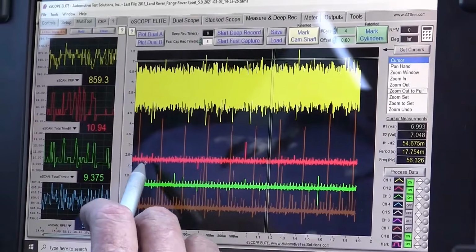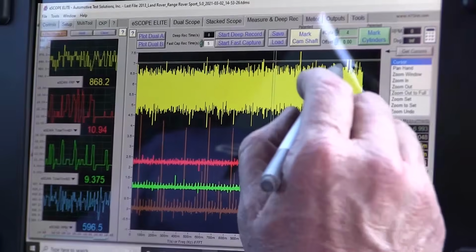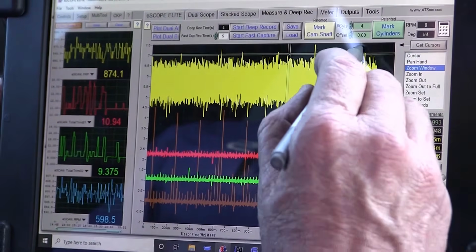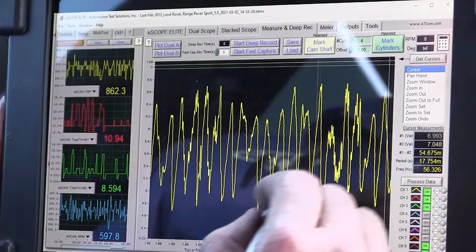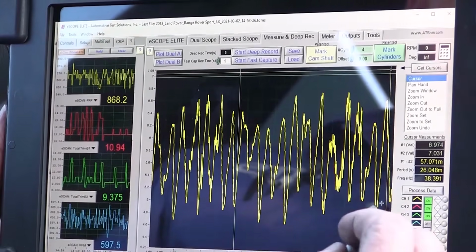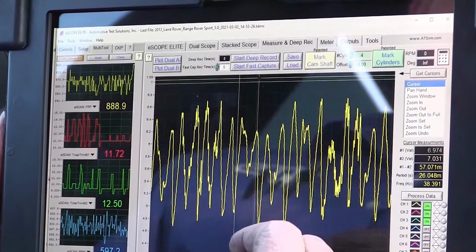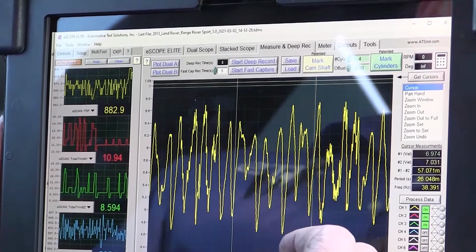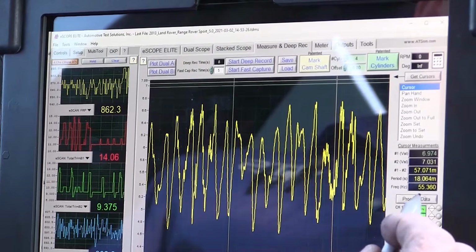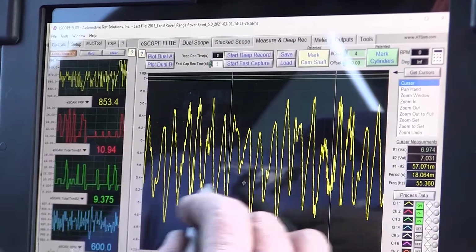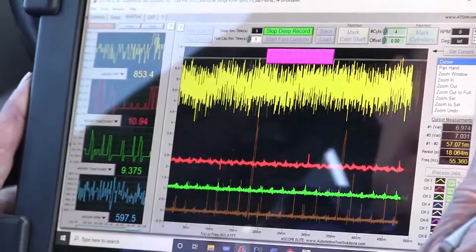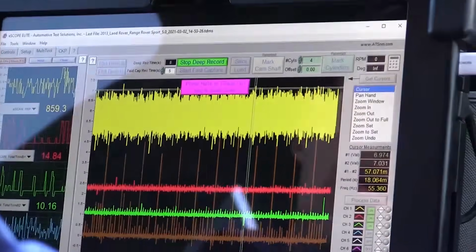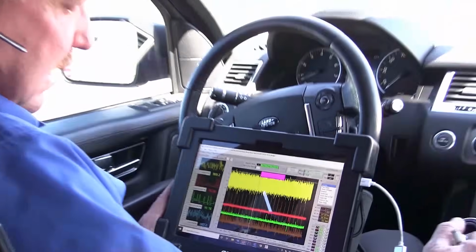Again, we have the fuel pressure right now, so we're supplying that pressure. Let's check one more time over here, because I'm trying to make sure the pump isn't changing its speed. 2, 3, 4, 5, 6, 7, 8. And again, we're at 55. It's the same. It's not changing. So what I want to do now is try to power brake it to see if it might do it here.